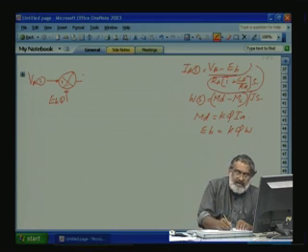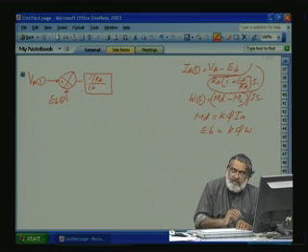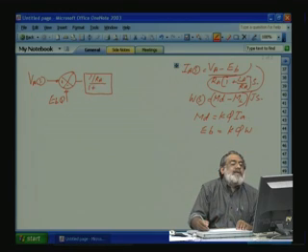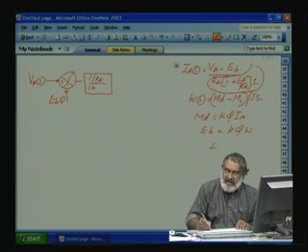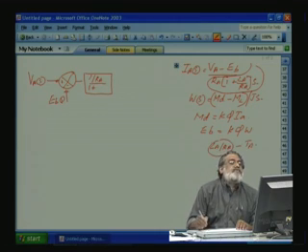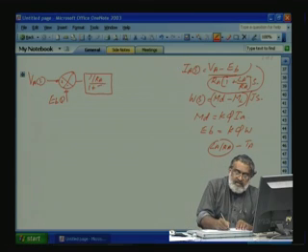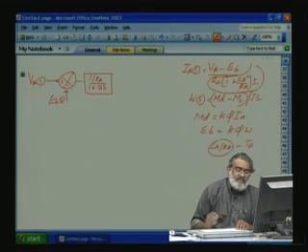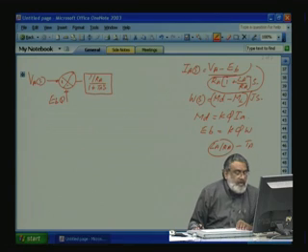So, this we can write like this, 1 by RA divided by 1 plus, what is LA by RA? LA by RA is the armature time constant. This we can write as TA, it has a unit of seconds. So, 1 plus TA into S, 1 plus ST form, okay.